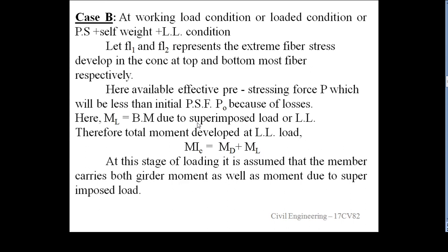Then case B, at working load condition or loaded condition, that is pre-stress plus self-weight plus live load condition. In that, let FL1 and FL2 represent the extreme fiber stresses developed in the concrete at the top and bottom-most fibers respectively.